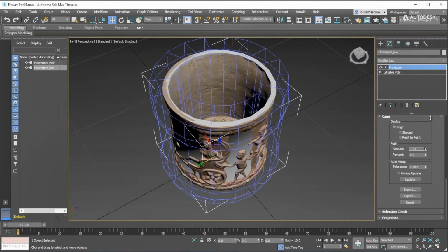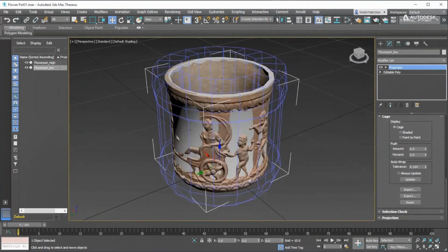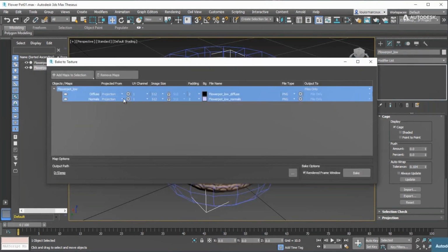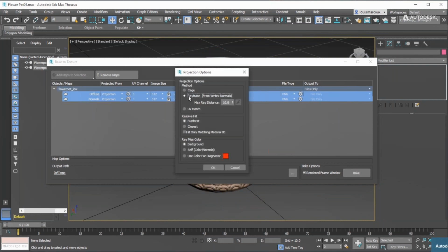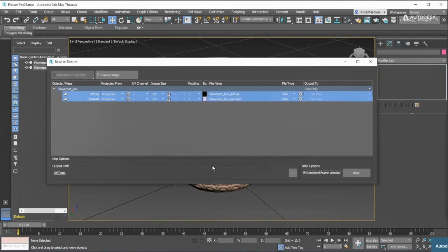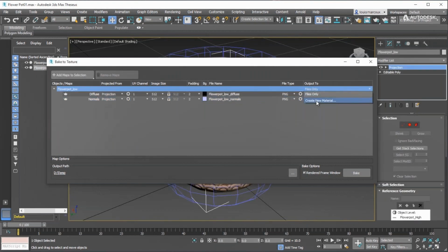This grid is going to be projecting the map on the object, and it has to be exactly in the center so that it projects from all 360 degrees, because this is a 360 degree around object. So once you've selected the size or grid of the projection, all you can do is click on ray trace from the vertex normals. These are some certain options which you need to select, and select the output file where the output material is going to go.